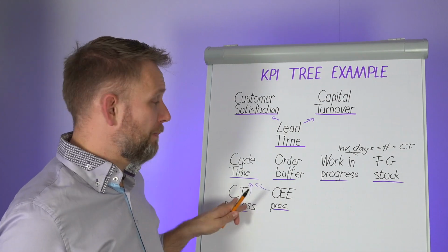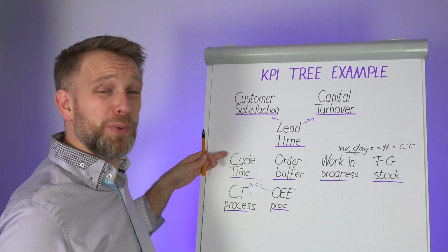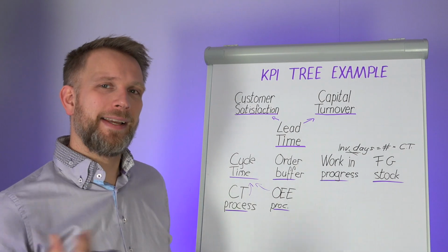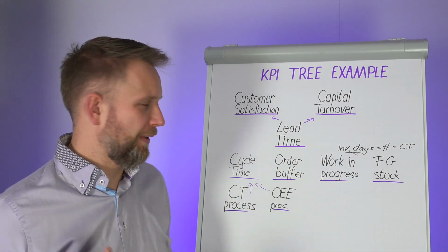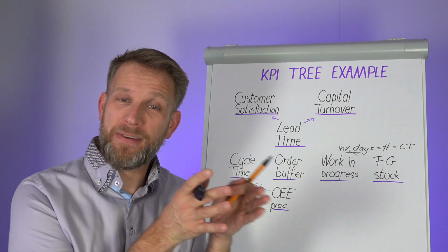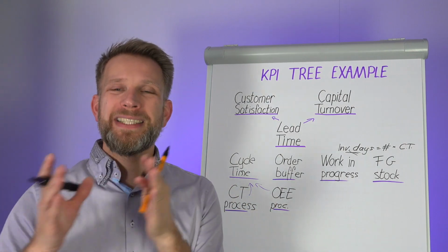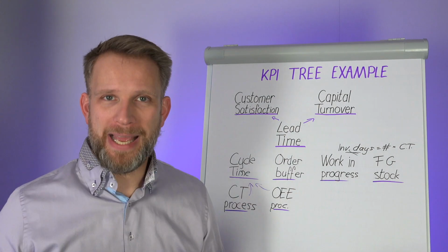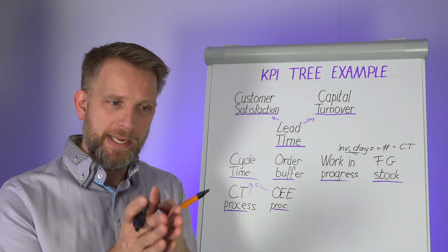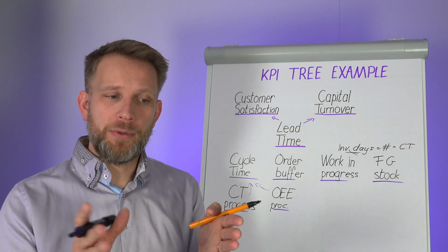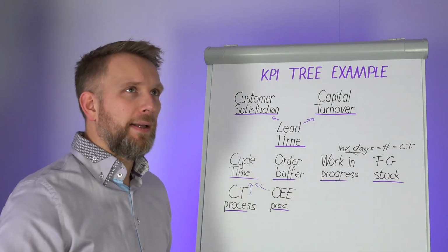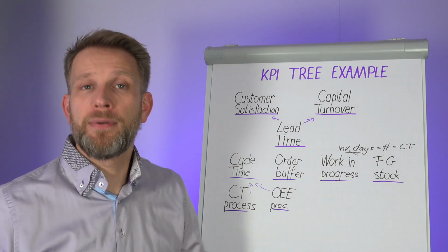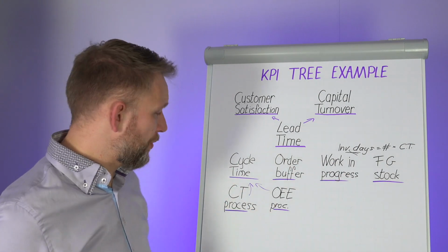Also important, by the way, in both of these, technically also in those one, but you don't really do that at that level, but definitely in these, you take planned downtime out of it. So in your OEE, your planned downtime is in there, but you have it as a category. In cycle time, you say, no, we take net production time. So we don't take into account planned breaks or planned maintenance or even the big changeovers, where you say how many hours did you actually have in your 8-hour shift to be producing, right? If you had an hour of breaks here and there and you had a setup of an hour, then you only had 6 hours of net time to be producing, put that in.